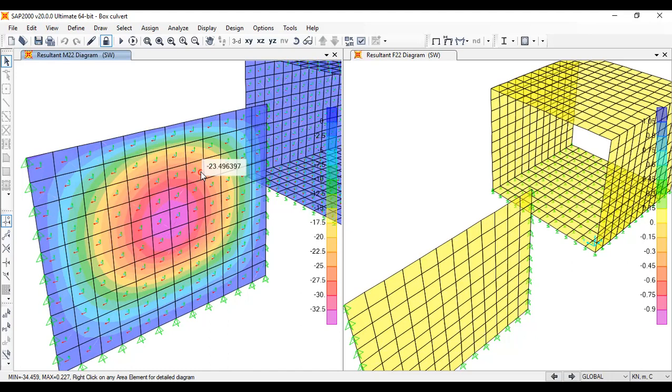Membrane forces and the out of plane moments are there, right? So there's some myth, right? If you consider a slab in a reinforced concrete frame, actually the slab behavior is plate, but still people use shell thin, that's okay, right? But people use membrane as well.